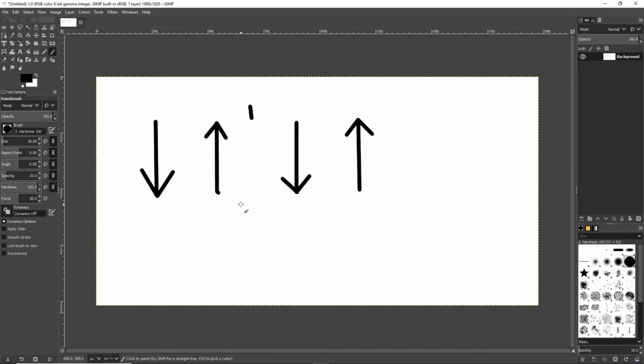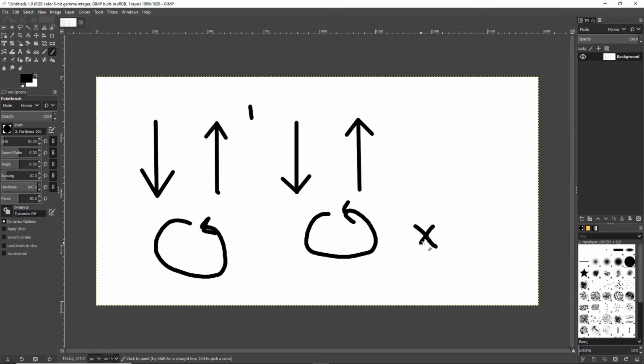One of the things I like to talk about is every time this guy goes all the way down and all the way back up, this crankshaft down here makes a complete circle. So it's one full rotation. And then we know we have to do it again. So across one four-stroke cycle, the crankshaft spins twice.